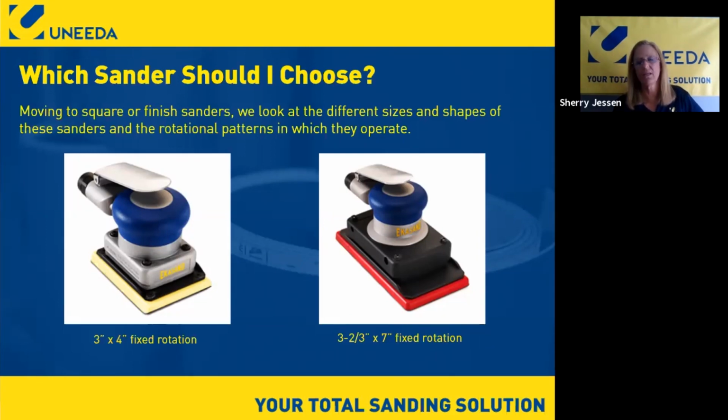The biggest problem that I see in cabinet shops with the 3x4 is on white wood. There's a couple of things that I'll tell you. On white wood, it's because it is a fixed rotation. I call it a straight orbit. I know that doesn't make sense, but it's just orbiting. There's no random to this sander. So as it's orbiting, it actually will catch and dig, and it will swirl. I've tried maybe 10, 12 different types of sheets and film, and there's really not one that's not going to swirl on raw wood or white wood.